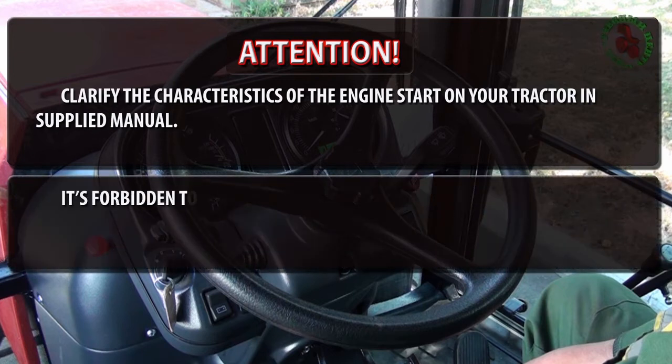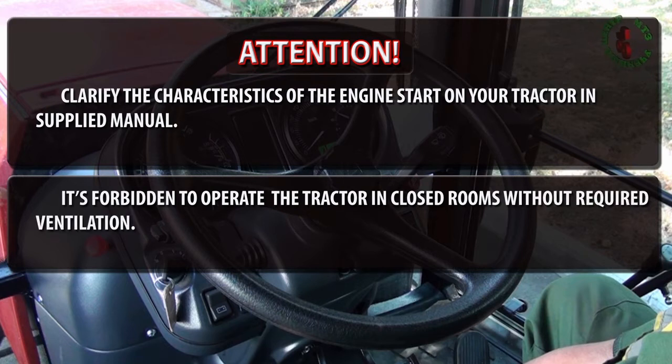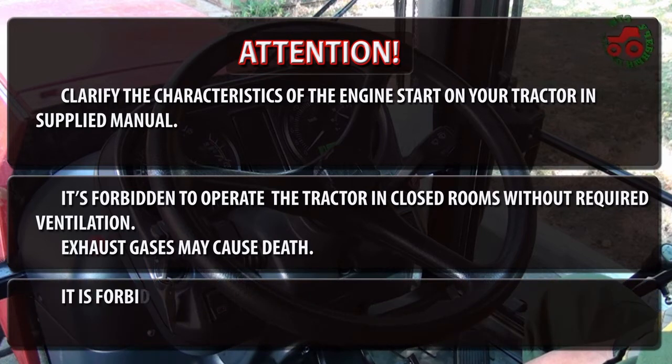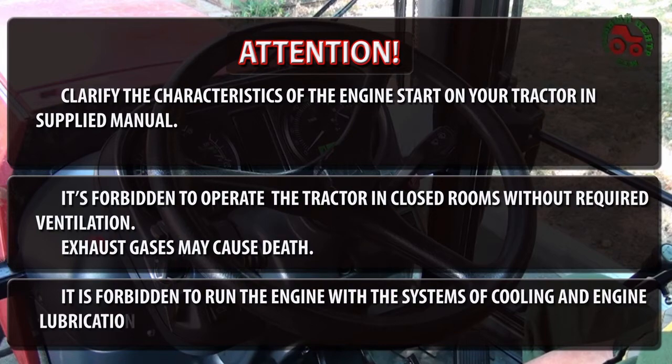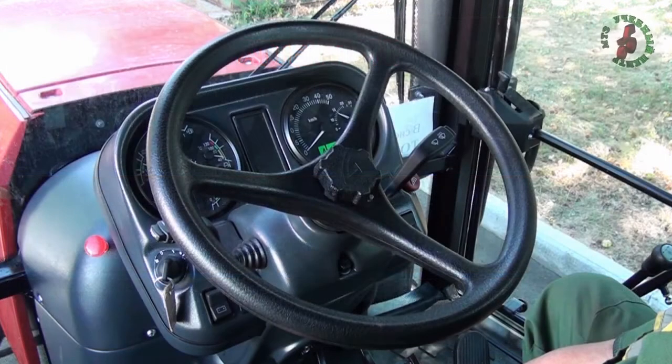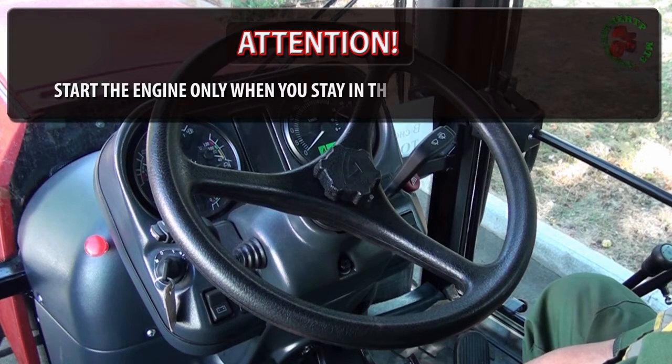It's forbidden to operate the tractor in closed rooms without required ventilation. Exhaust gases may cause death. It's forbidden to run the engine with the systems of cooling and engine lubrication unfilled. Start the engine only when you are in the operator's seat.